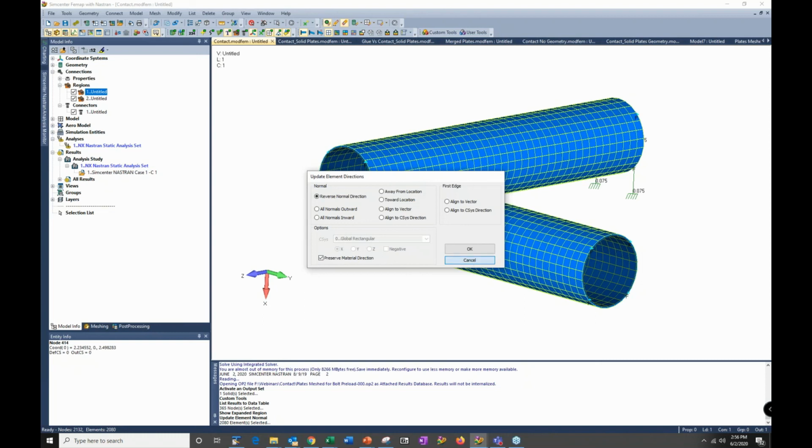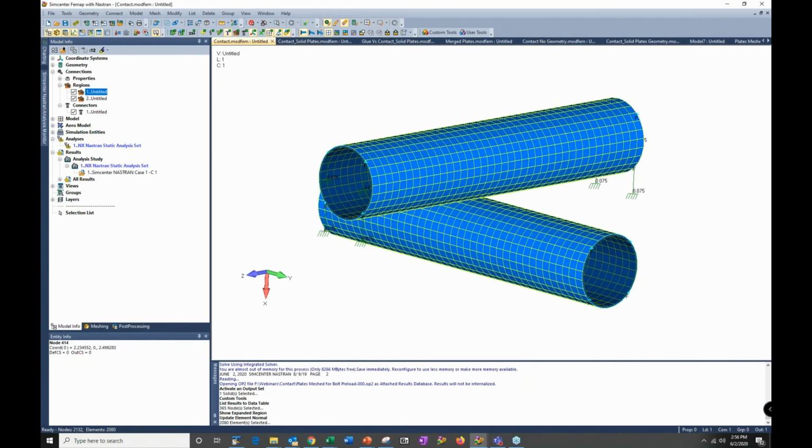If you mesh the elements between the surfaces before defining the contact surfaces where the surfaces meet, will the contact surface effectively unmesh? No, it does not unmesh anything. The contact is defined either on the element faces or on the surfaces, and it would be meaning your elements have to be associative to the geometry.